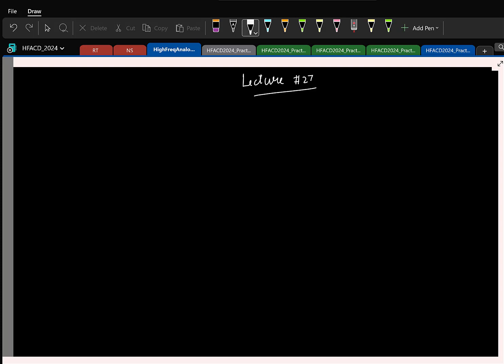Okay, let's start. In the last class, we started to look at the first non-ideality we encounter, which is basically the mismatch among the elements. We saw that for passives, the mismatch is quantified as a relative mismatch. Since it's a random quantity, we are interested in its standard deviation. Similarly, for the capacitor, we have the relative mismatch. Coming to the transistor, the current factor mismatch is again quantified as relative, but the threshold voltage is not normalized.